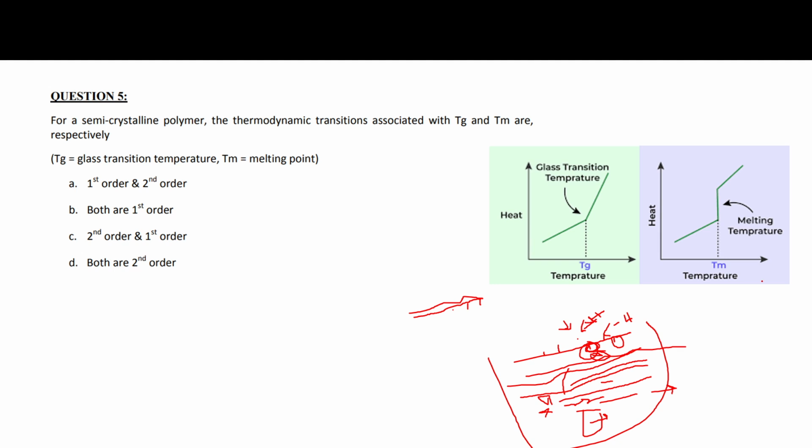Like if your polymer sample has a Tg of around 10 degrees centigrade, and you use this material in our country, where the temperature is generally above 20 or 25 degrees centigrade, your material is a rubbery material, so you can apply this material here. But if you use the same polymer in some country like Siberia, where the temperature is very low, like minus 10 degrees centigrade, then your polymer becomes glassy there, so you cannot use it. Your polymer needs to be flexible.